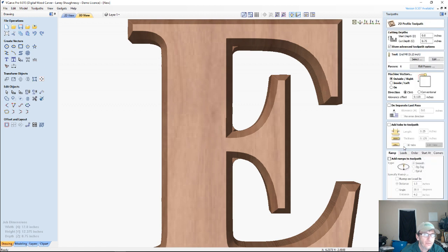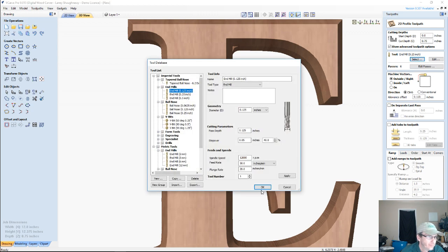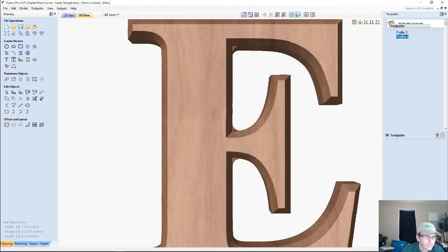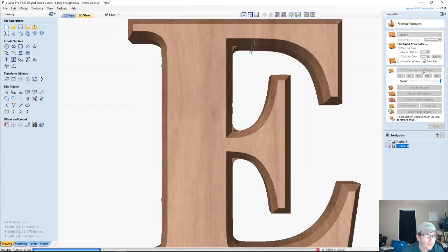If I were to have used a smaller end mill, then that internal cut on those 3 edges is significantly reduced to where it's almost invisible to the eye. But I'm anal, so I would do a little cleanup, little sanding and a little file and everything, just to square those corners up.